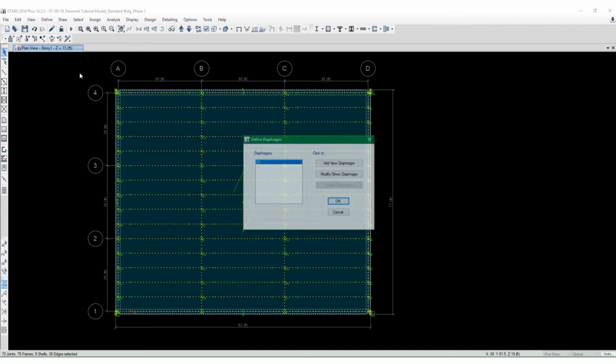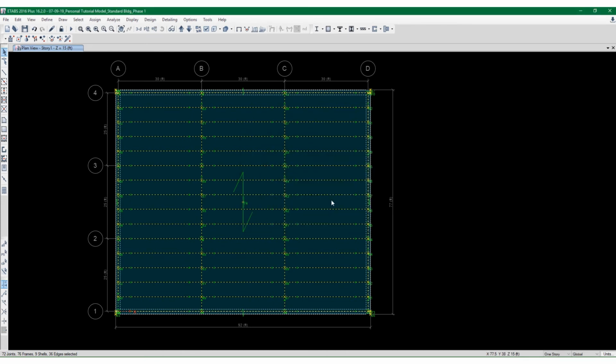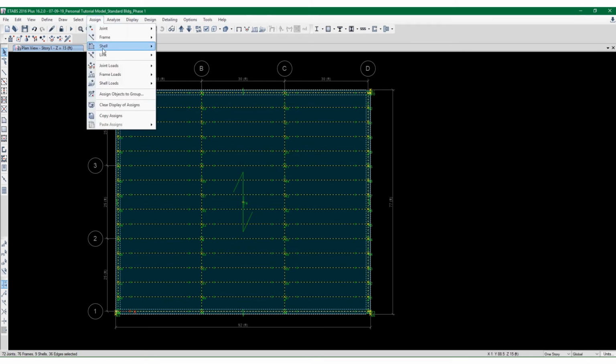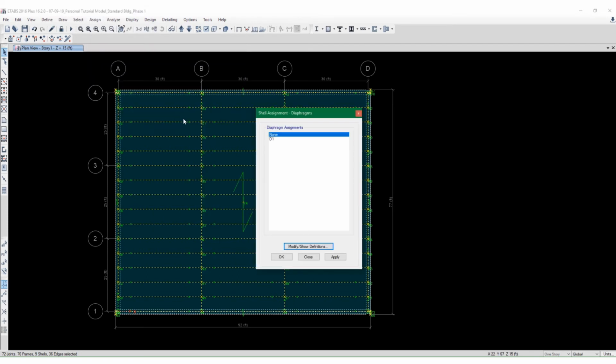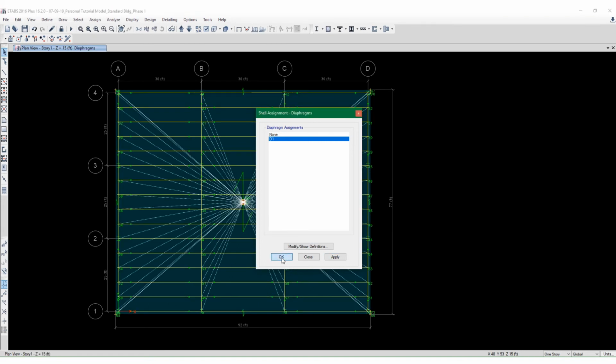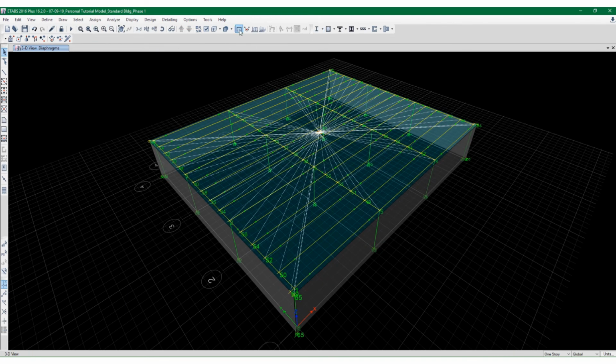Okay, so I'm going to go ahead and change my diaphragm property to rigid. And when you do that in ETABS, you actually still need to go back and reassign, if you will, that diaphragm to those same elements. If you do not do that, notice that it doesn't take just because I changed the definition of it. In one area, I actually have to reassign it. All right, so that's been done. Now with that modification, run the analysis again.